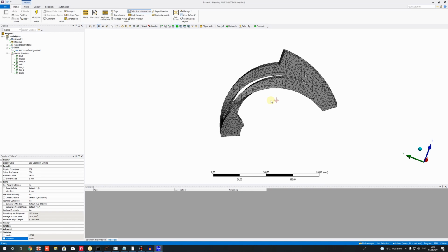You have to increase the number of elements of domain and perform simulation again, repeat it, and you will get some performance characteristics of impeller for different mesh cell sizes. The more elements you set, the more accurate results you will get from a numerical point of view.